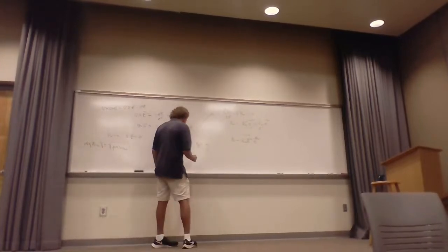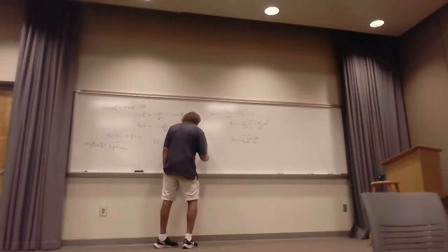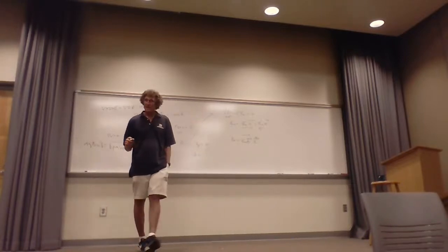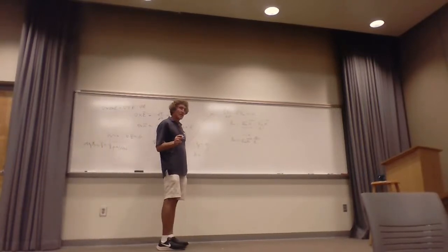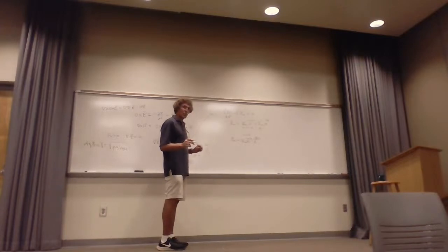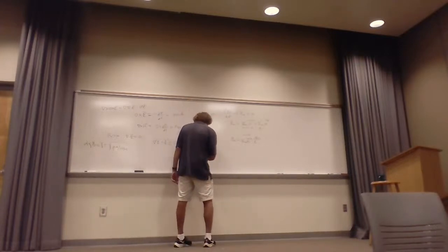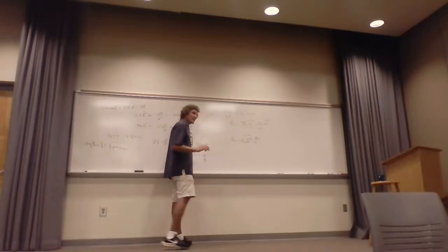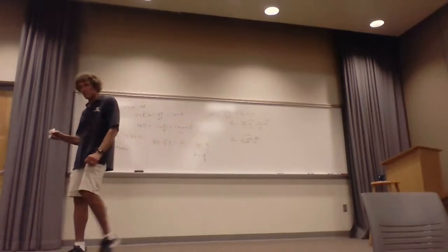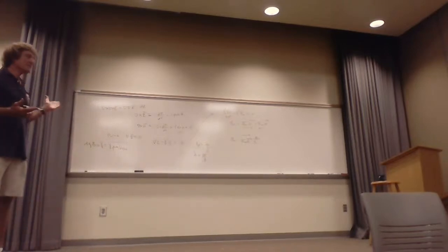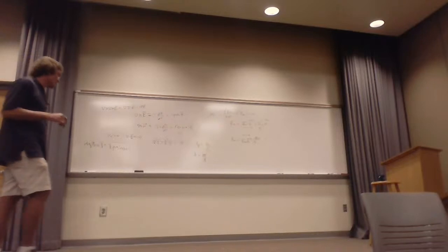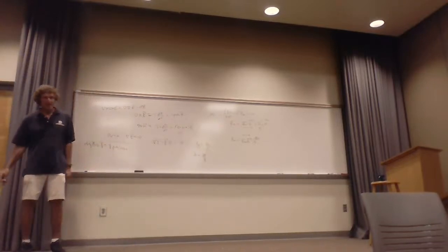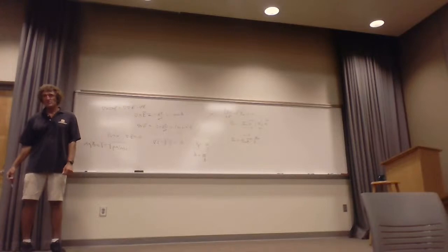And what is the wavelength always? Well, that's assuming the speed of light. In general, you know this, right? Wavelength is 2 pi over beta. Jacob said it right, because beta is radians per meter, right? So wavelength times beta has to be 2 pi. It's a full 360 degrees or 2 pi radians. That's how you get it. You always use beta. And remember, beta can be a lot different than what it would be if it's free space. Just remember those things.